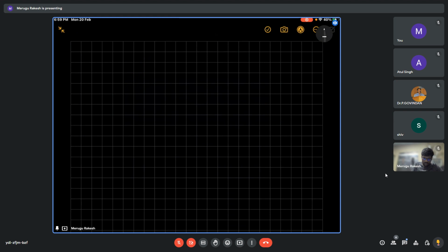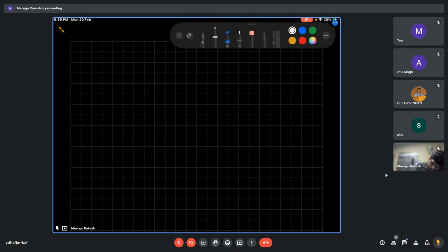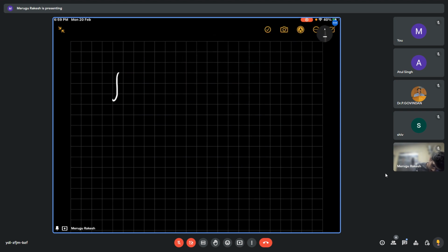Okay. So now we have an equation: integrate 0 to t, Ag times the square root of 2g(H - h) casting... dt is equal to integration 0 to hc. So the height of the casting, this is the pouring time, into this area of the casting multiplied by dh.